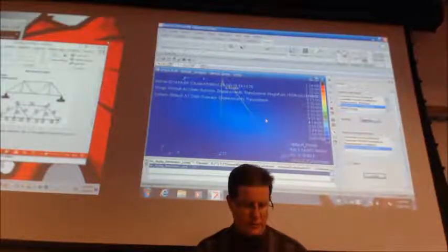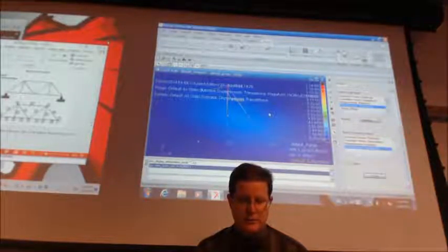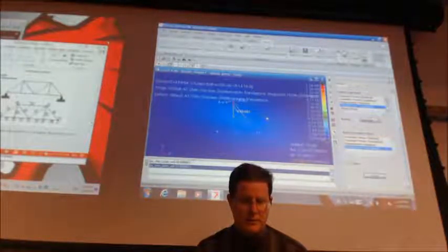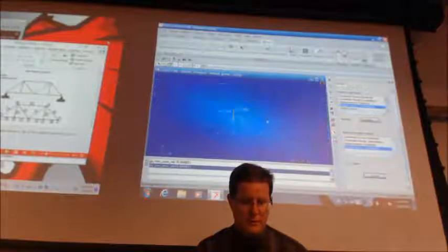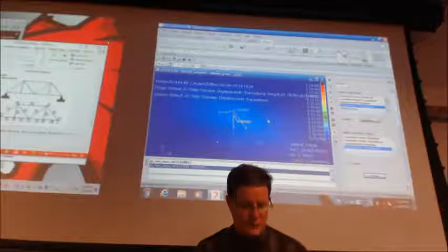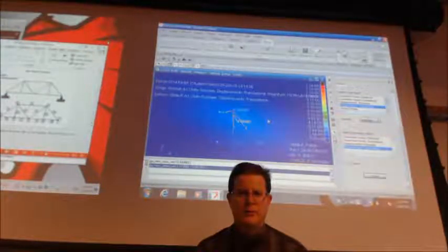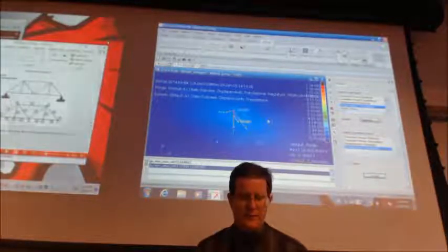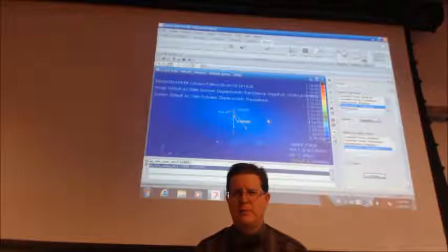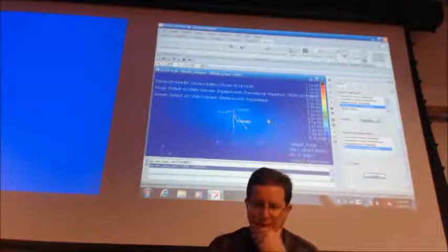Okay, so now the question is, it's kind of small. How do you just do that? If you hold down control and push the middle mouse button, the roller, you can zoom. And if you do shift in the middle mouse, you can pan around. Oh, sweet. Okay.